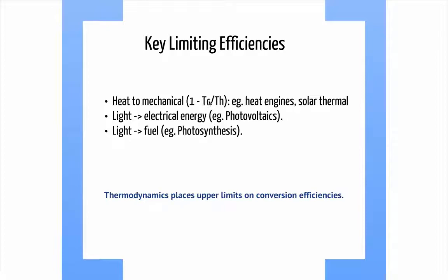But if the temperature of the cold part is very small and the temperature of the hot part is very high, then this ratio goes to very small values, which means that you're getting close to 1 or 100% efficiency. So you really want to make the cold part very cold and the hot part very hot to get this efficiency to be high. Of course, there are problems with that, as we will see later on.